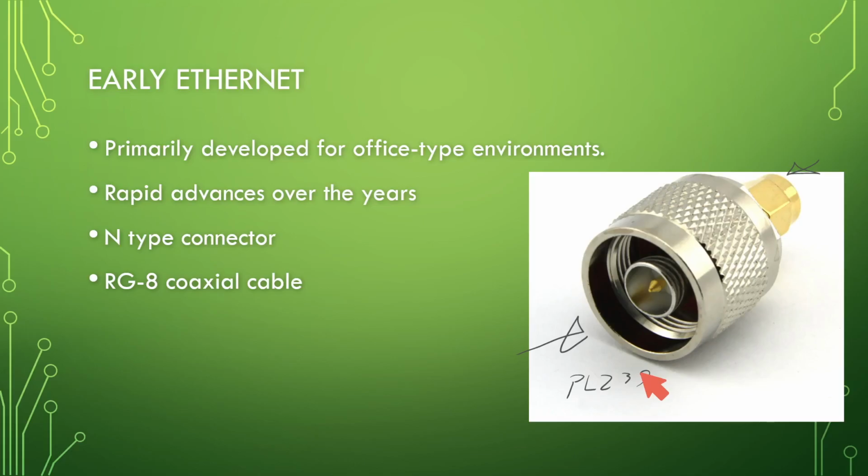Unluckily, coaxes also have different impedances. So RG6 is 75 ohm impedance, where RG8 or 58 is 50 ohm. And the impedance does matter in the long run. It screws with things. You gotta be freaking kidding me. So that is just an absolute pain in the rear end, if you ask me. So again, just something to keep in the back of your mind.